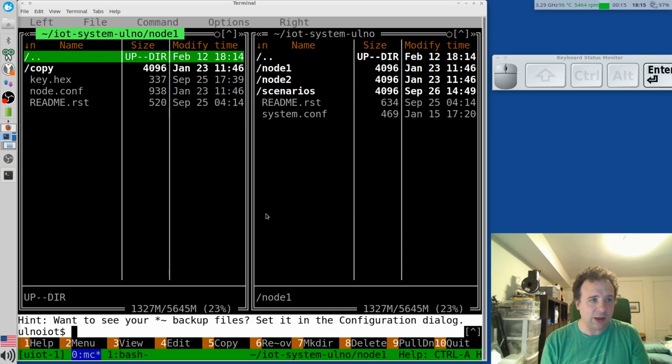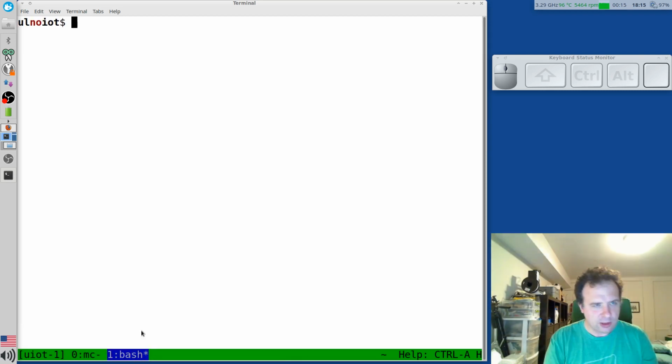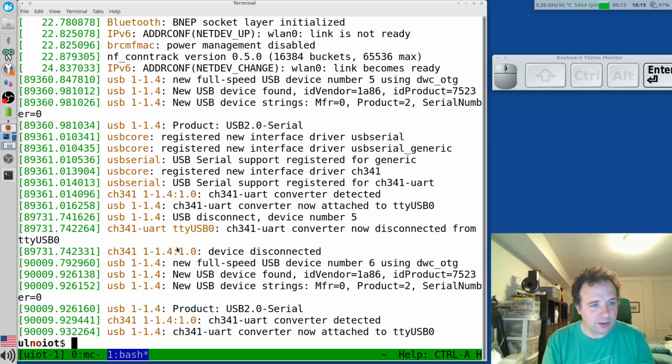And then you go into node 1 and you can then trigger the initialization of it. For this we actually have to do some hardware. So we have to plug the little Wemos D1 I have here with the green cable into the USB port of the Raspberry Pi. And if you're not sure if that worked, you can look in a new window. The command to see what happens on device level is dmesg. You can just type this in here and you will see down there, oh, there's a new USB device. It's exactly what you wanted, so that's attached now.